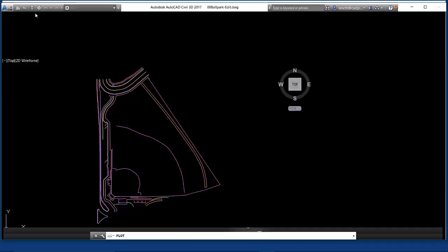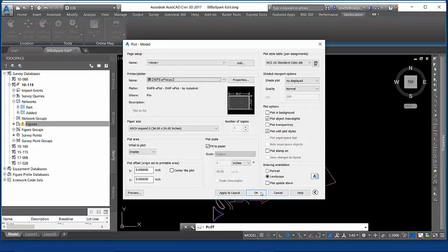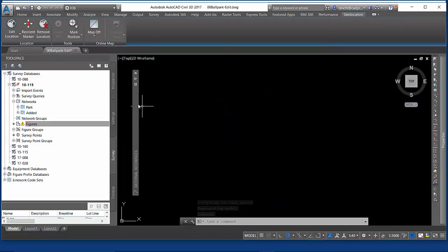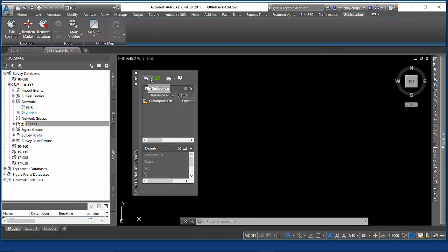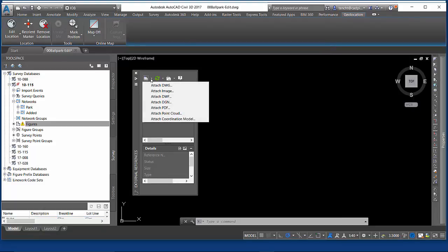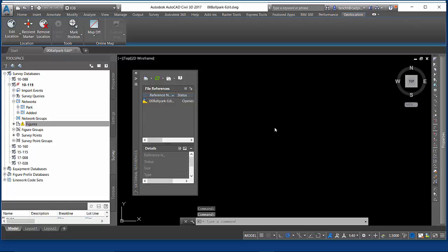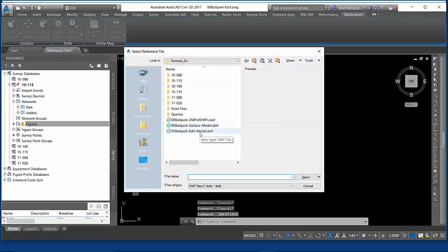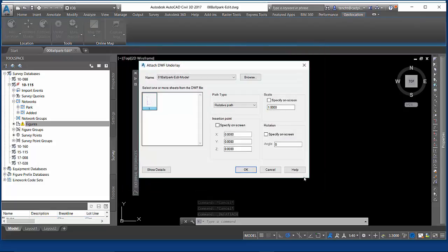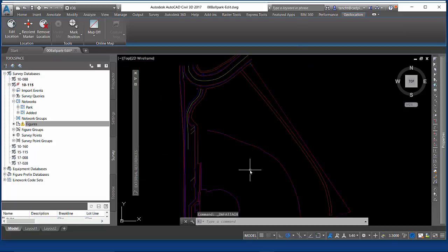That looks like what I want to be in my DWF. I say okay, generate my DWF, and I get a result. So now let's see what that result looks like. Could do this in AutoCAD. I'm just going to do it once again in Civil 3D. Bring in my exported DWF. Key issues here, I want to make sure nothing is specified, so it's going to 0,0. We'll end up in the same space.